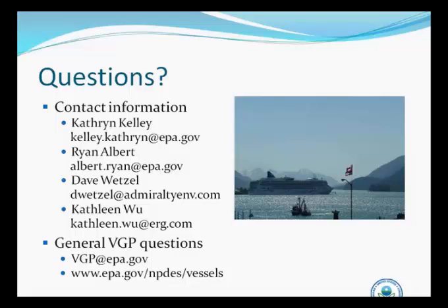And this is actually, I'll expand on this a little bit. This is a question we get a lot. For example, for bilge water, if you're a vessel that does not discharge bilge water within waters of the U.S. or within 3 nautical miles, do you have to do monitoring? And the answer there, again, is no. So if you are not discharging the effluent stream, you are not required to do the monitoring. And just to clarify, so that you don't have EPA compliance folks knocking on your door after 2 years, just be sure as part of your annual report you check that you did not discharge that monitored stream into U.S. waters.